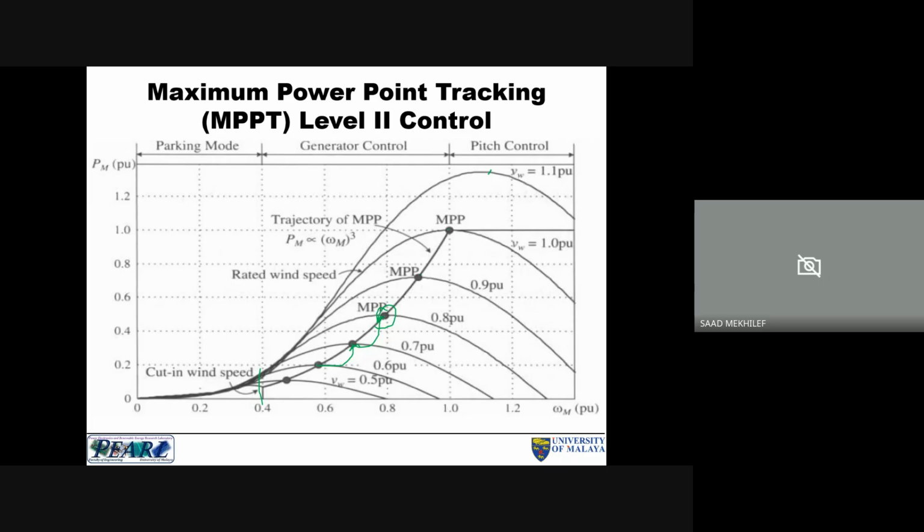So these are the two main characteristics that we use: the constraint between the step size of change, the speed, and the oscillation, because the oscillation is reflected later on as power oscillation. And the speed means maybe we lose some power. Sometimes we may prefer to lose some power rather than having power oscillation.